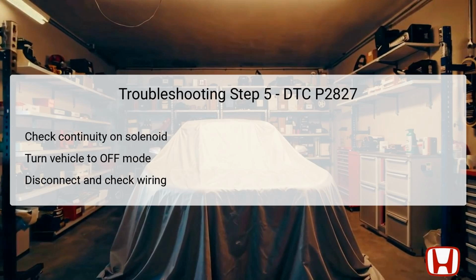Test point 1 is at line pressure solenoid valve A 2P connector number 2, while test point 2 is connected to body ground. If you find continuity between these points, it indicates a fault with the line pressure solenoid valve A itself, which necessitates replacing the secondary valve body.